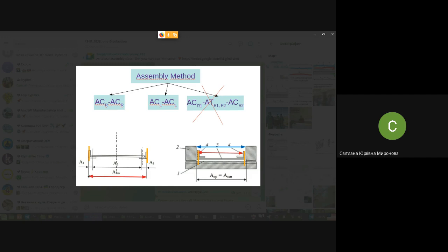The designer is interested in the outer surface only. But during assembling, we locate onto these holes in order to provide the outer contour with some accuracy. That is the idea of locating assembly component to assembly component.